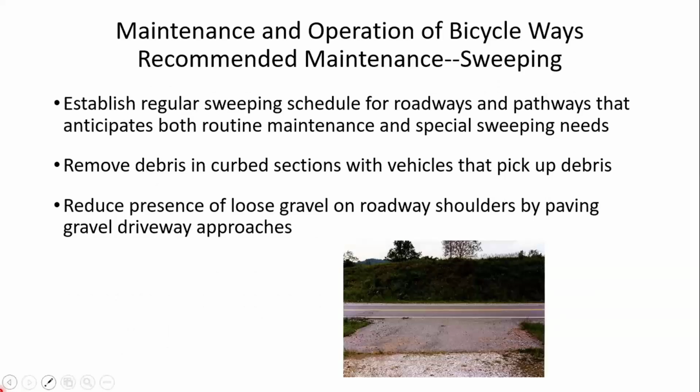So what about some recommended maintenance for bicycle ways? One would be street sweeping. Establish regular sweeping schedule for roads and paths that anticipates both routine maintenance and maybe special sweeping needs. For example, maybe after a major rain event or storm event or something like that. Remove debris in curb sections with vehicles that pick up the debris.